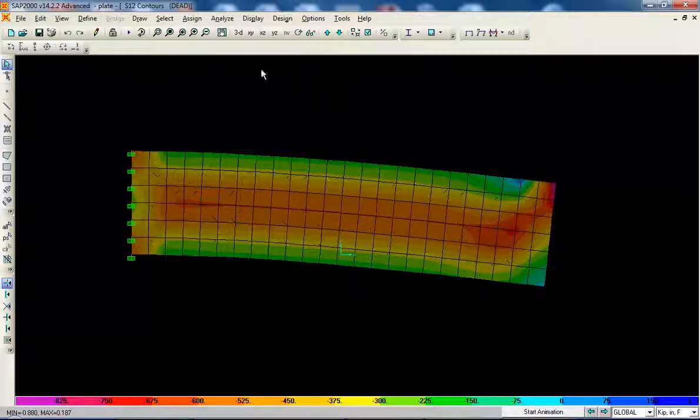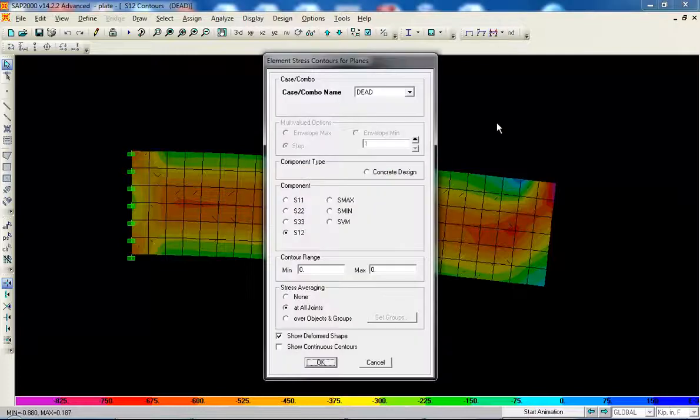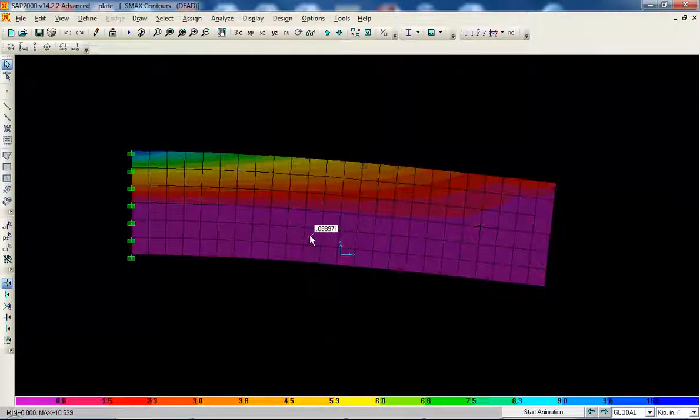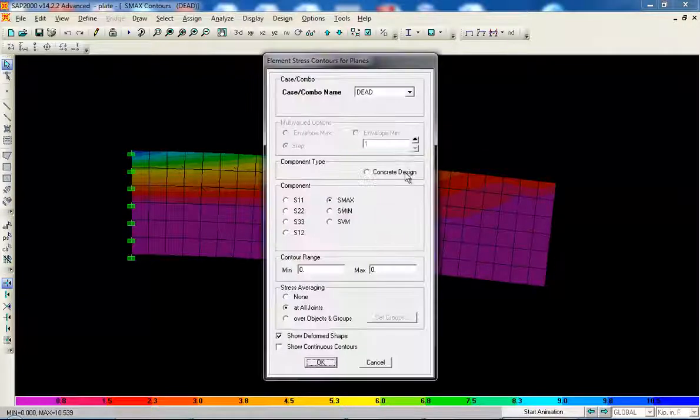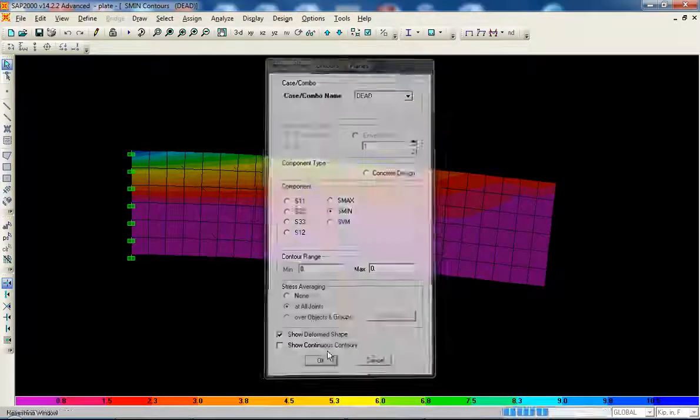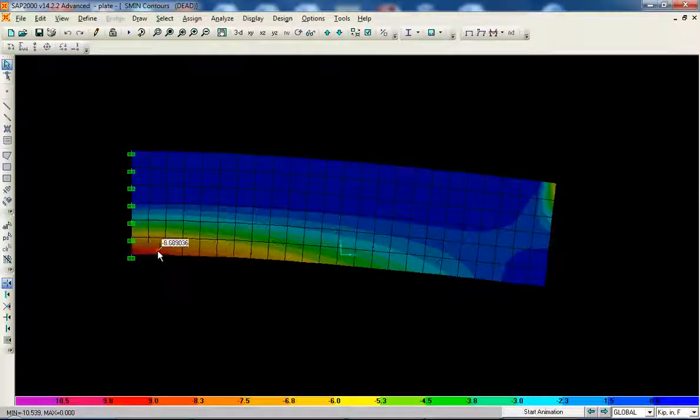And now let's take a look at the maximum principal stress, which is tension. So it's tension here. And those are like 0 because they're mostly in compression. The maximum compression principal stress is mostly here. And then you have some concentration here because you're compressing it.